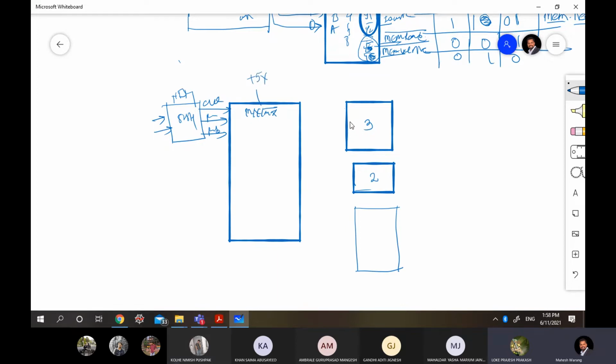For a latch we actually require two control signals. Which are they? Not ALE, but STB and OE bar. So OE bar we will be grounding and STB we will be giving ALE. After that, it is ready. Now give it all the multiplex lines. Which are the multiplex lines? AD0 to AD15, A16 to A19, S3 to S7, and BHE bar/S7. Give these to it.